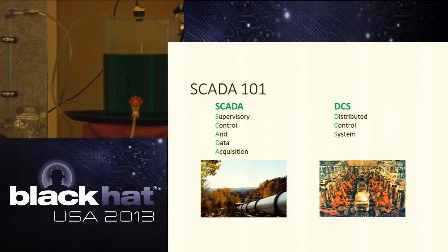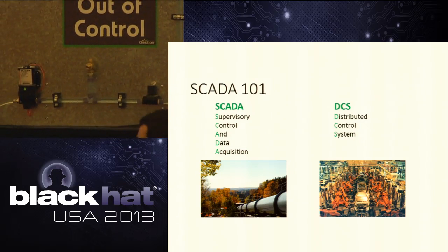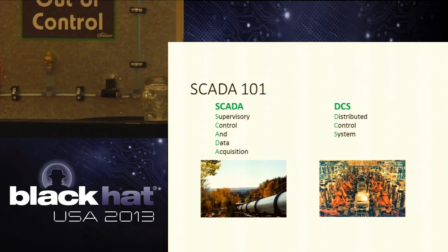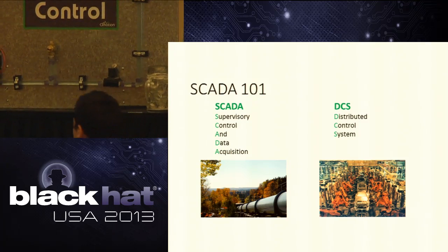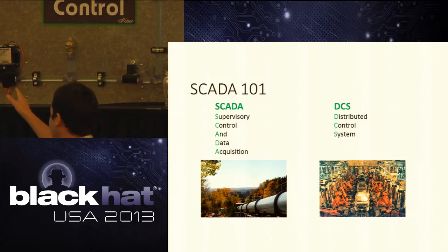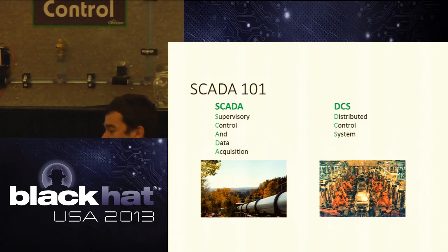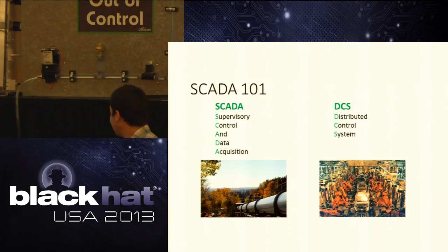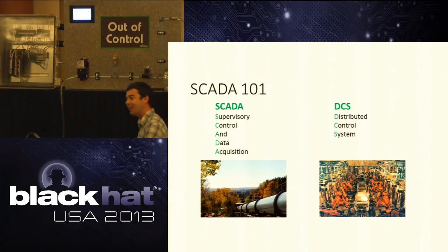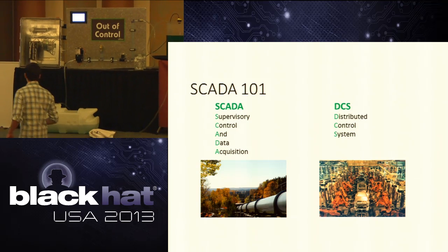One thing that we also have here is this little brass guy, a pressure safety valve. You see those a lot in industry to prevent overpressures, but sometimes in production you'll have this pump and an isolation valve with no PSV in between. But we had to put one in just because we don't want to spray water everywhere. So we put one in for that.